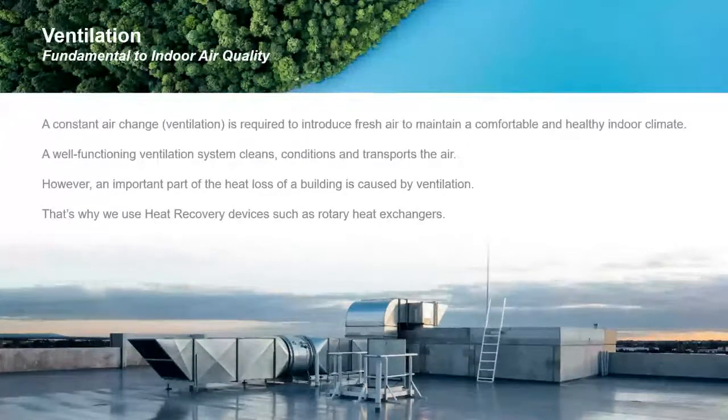So whenever we increase the amount of outdoor air that we're putting into these spaces, it requires an additional component. So in Stockholm in winter, it's going to require some additional heating, whereas in Dubai in the summertime, it's going to require additional cooling. So those types of processes that we're applying to this air are creating pollution at some point, unless they're coming from sustainable sources.